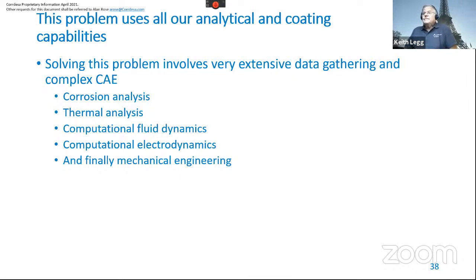Thank you. Last question from Dominic Shore. If you repair the anodic coating without removing the old coating, is it hard to quantify the exact surface area of the aluminium alloy exposed from the damage? And is it difficult to assess how much current must be applied to provide a suitable coating? Or is this a potentiostatic process?